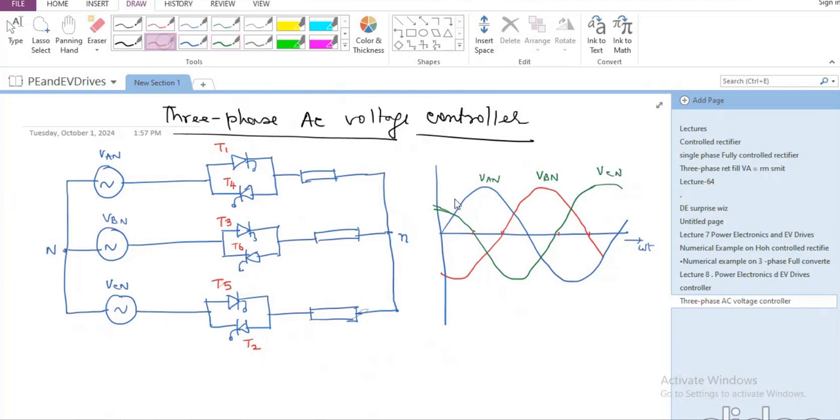And at any instant of time, if I am looking at these AC voltage controller devices being replaced by a diode, it would be sinusoidal, because if I have a diode, it will work during positive half cycle here. Similarly, this diode will work during negative half cycle here. So it is as good as having a simple copper wire connected. So the firing angle in this particular case will be calculated from the point where the devices would have started conducting had they been diodes.